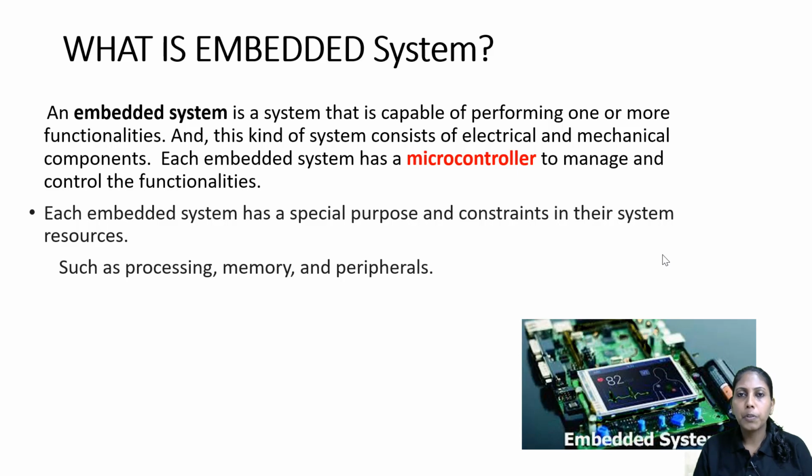But right now, what you are going to do is write a program on the host machine only. You'll be writing the program on your laptop with the help of that IDE. I'll tell you the different stages for it, but finally that IDE will convert this program to a hex file, a dot hex file. So what is this dot hex file? It will be the compressed version of whatever high level program, whatever high level language you used, can be C, C++ or whatever it is. So you write the program using this high level language.